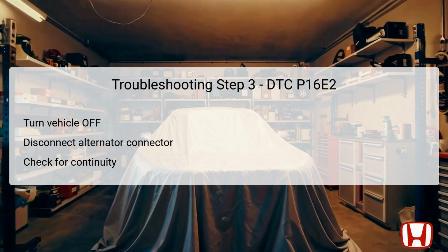Perform this test while confirming that the vehicle's electrical systems are completely powered down, which will ensure there are no falsified readings due to live circuits. If continuity exists, it means that the connection to ground is intact, and you can proceed to subsequent troubleshooting steps.